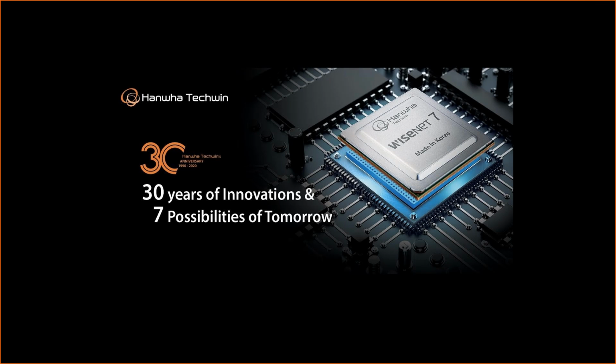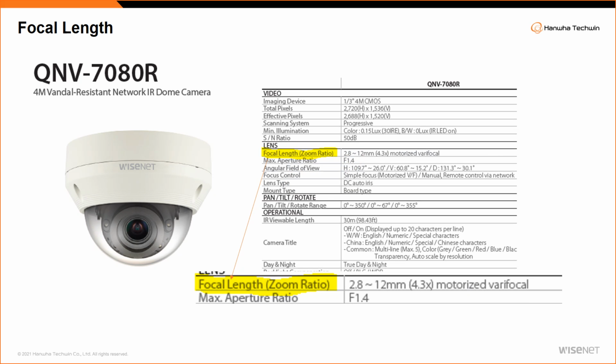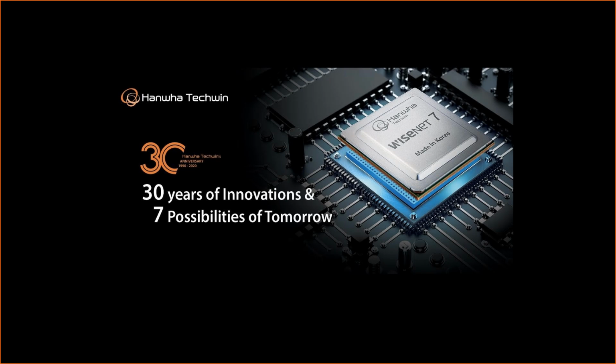All right, so most, I would say 95% of your typical project locations, you will keep the camera at a wide angle at 2.8 or 3. You will leave it at that location itself. All right, okay. Of course, there are projects where you need a longer lens. Maybe the distance from the camera to the door is very far. Maybe in a hotel, the nearest place to mount a camera is like 20 meters. The ceiling height is very high. You cannot put the camera. In that case, you will, okay, let me explain this point.